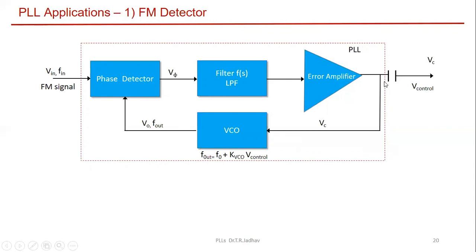So what we have done? We have just used a coupling capacitor here at the output of error amplifier, and we have derived the output as demodulated output. So not unmodulated, it is demodulated output.